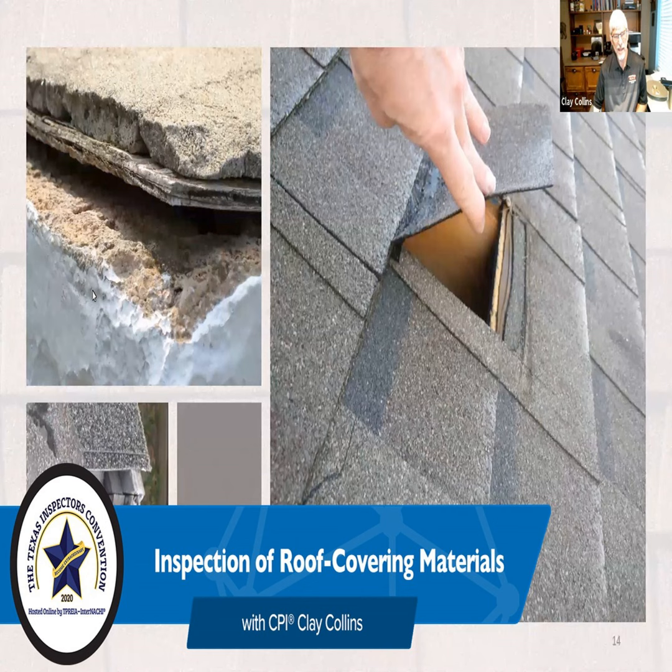And you can see a re-roofed house with a narrow top deck board, and it's just torn to pieces. Well, these additional H-clips aren't necessarily going to stop the additional damage, especially if there is a very narrow 4 to 6 inches deck board there.